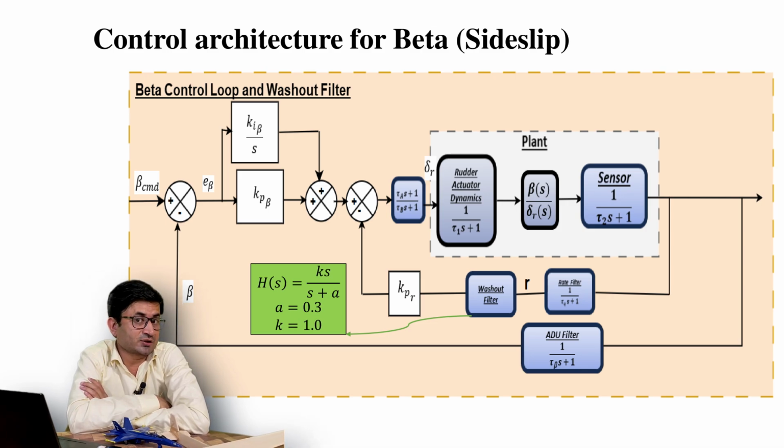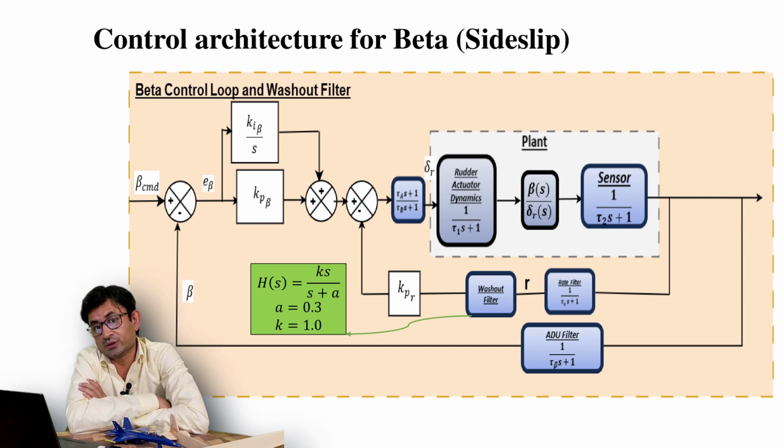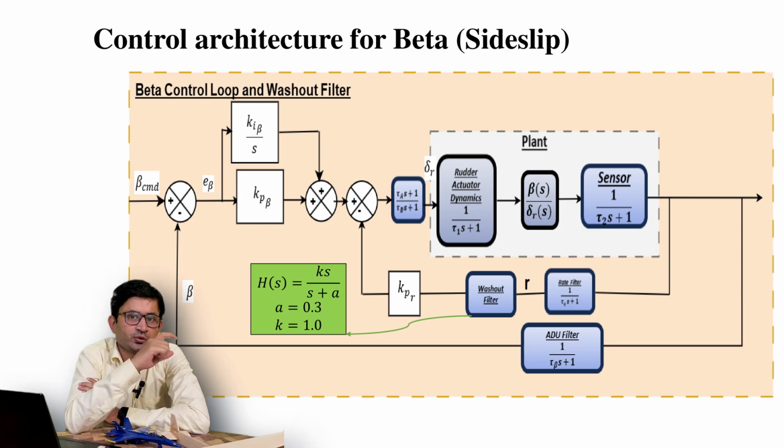That is also a problem when the pilot flies, because the pilot will not like this kind of flight. It is too stable, and the spiral mode is already slow, so it takes turns and banks slowly. So that is again the problem. Actually, you can eliminate this problem by using a washout filter.